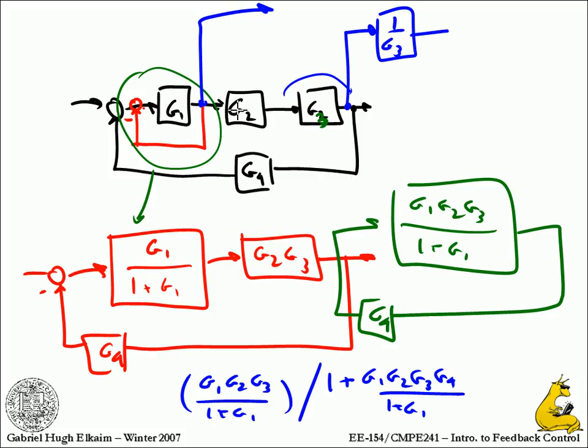Right? Because whatever comes out of this one gets multiplied by G3 and comes out here. So therefore I can pull that cap out, which means I can then move this guy to the other side of that. Do you need to do the same thing with that other one? Right. So in this one I would pull out 1 over G2, G3 and move it over.